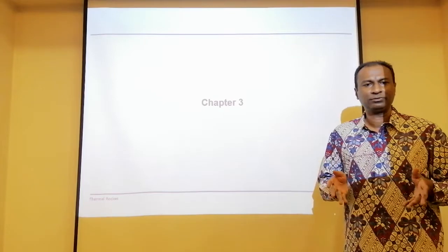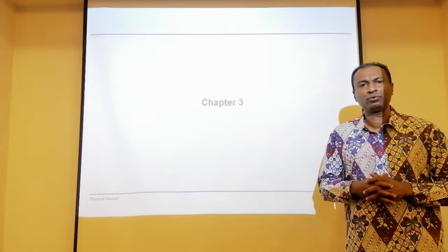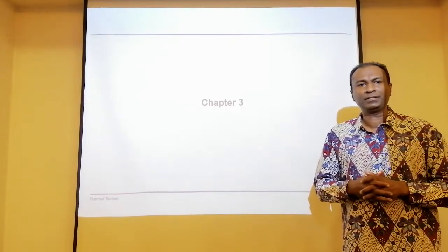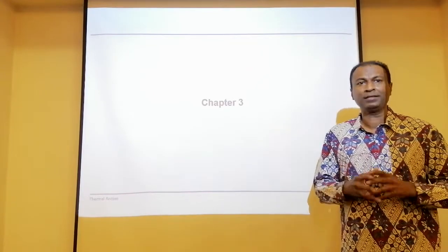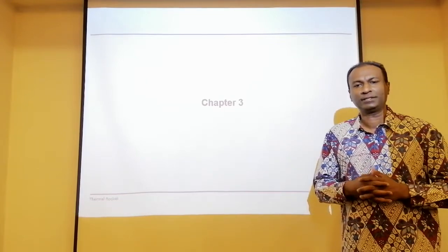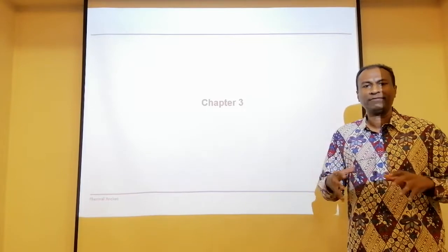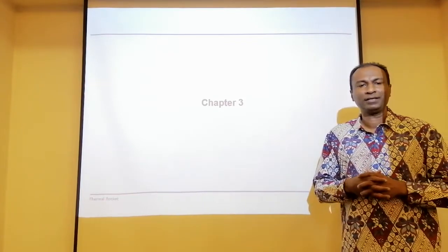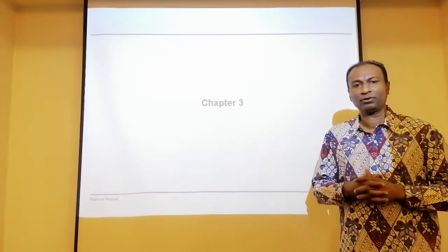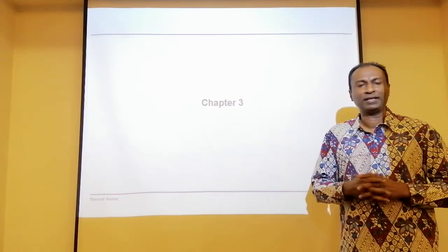As we have seen in chapter 2, we focused on rocket performance, and one of the most important parameters in the rocket equation is the effective exit velocity (CE). I've mentioned before that deducing the CE is not easy because it's an in-flight performance. But when we want to manufacture a rocket engine, we have to estimate the actual exit velocity at the engine level. Then we need to apply a tolerance during the flight to get the actual CE.